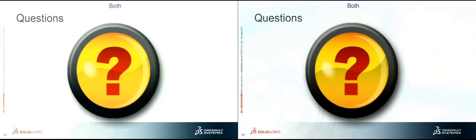Anybody else? On your explosion, early on in the process there, you talked about turning off the mates. Yes. You do the explosion and wizard, you don't necessarily. That's correct. And you notice one difference. Over here, I have change bars between the key points. In Composer, you just have the key points. Those change bars are different colors depending on what they are. When I use the animation wizard, they were orange bars, which say, I'm ignoring the mates. I'm just going from here to there.